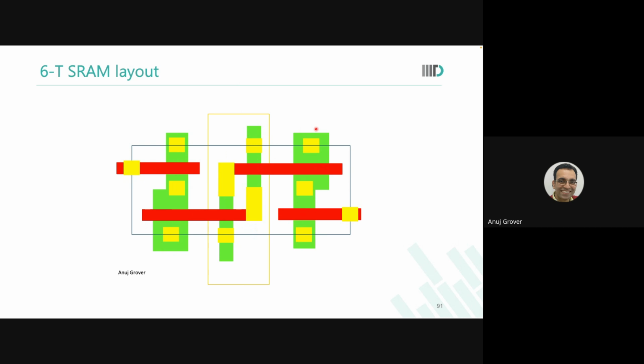See, all of you have made layouts. Have you noticed that the contacts that you draw are always square? But now I have made a rectangular contact. And you will notice that it is only inside a memory cell that the technology team will allow you a rectangular contact.